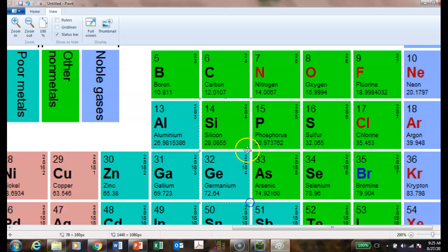We used to use a lot of carbon, but the problem with carbon is it is highly affected by heat. And carbon's pretty neat because you can spread it out, and its opposition goes up, and you can compress it, and its opposition goes down. These used to be the first voltage regulators. They called them carbon pile regulators that regulated the output of the generator. So if the output tried to go up, the carbon pile would compress. It was made up of a bunch of discs.